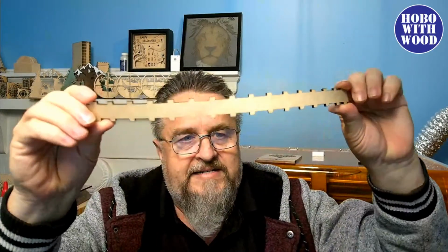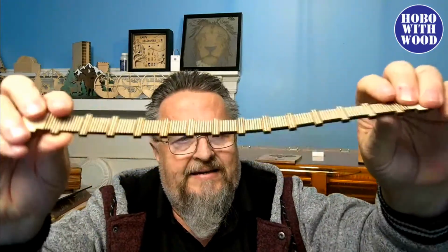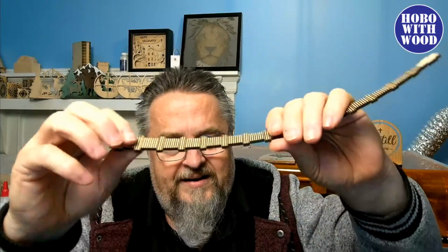Let me get this in here, if it will. Okay, I ain't gonna try to do it. It's not glued up. But I've got a solid piece here that I can bend, and this one is kind of dried up. But what I did, if you've ever seen any of the sheetrock workers, when they try to make an arch with sheetrock, they can do it out of a solid piece of sheetrock by scoring the back side of that sheetrock about halfway through and making some V cuts in it so that it can flex and bend and keep the other side intact. And that's what I was doing here.